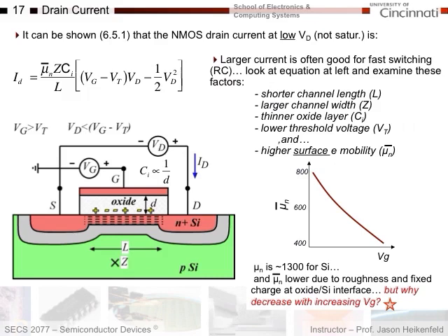Let's finish up with a couple of the currents for MOSFETs. We talked this whole time about threshold voltages. I should give you some equations for current flow though. So it can be shown, meaning I'm not going to derive it, that at low drain voltage, meaning not in saturation, when you are in your linear regime, where this is just acting like a slab of conductor, V equals IR, more voltage, you get more current, that your current can be predicted as follows.